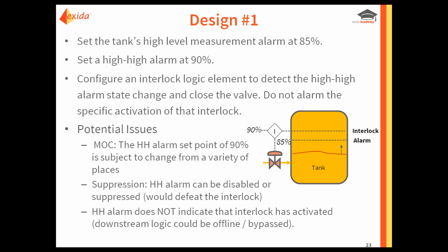The other problem with this implementation is that the high-high alarm doesn't actually indicate that the interlock is activated. We don't really know whether that has happened because that's downstream logic that we're not looking at in the way this is configured. So we don't really truly know the status of the interlock.